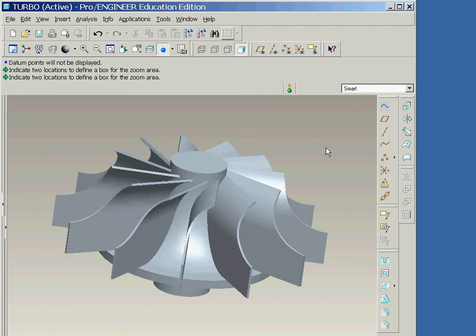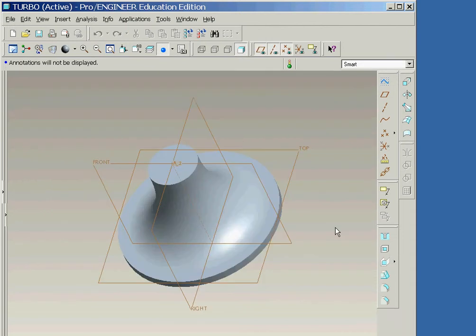In this session, we'll illustrate how to create a radial pattern that is based on a sketched feature. During the creation of the pattern leader feature, we'll use the makeDatum operation in order to create an angular dimension that will then be incremented to produce the pattern. We'll begin at a point after having created a revolved feature that represents the hub of our turbocharger fan wheel.